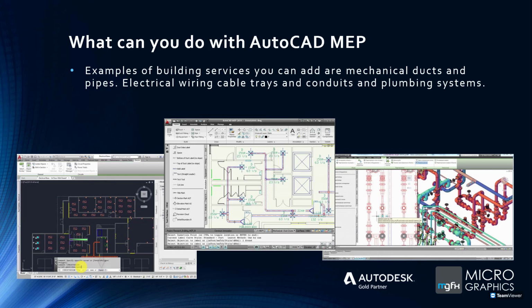Obviously, the advantage of that is that you can count them, you can count the lengths, you can very easily tag them, giving them names, dimension them, that sort of thing. All right, because they are objects. Right, then also on the left-hand side, there's some light fittings which you can connect using electrical wiring, cable trays, conduits, that sort of thing. Also, again, count them and cost them.